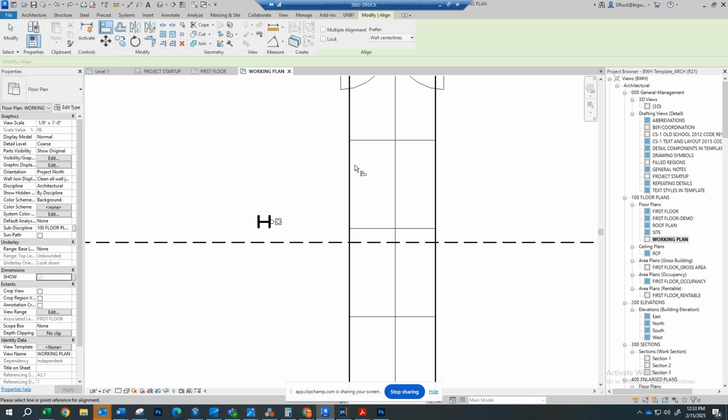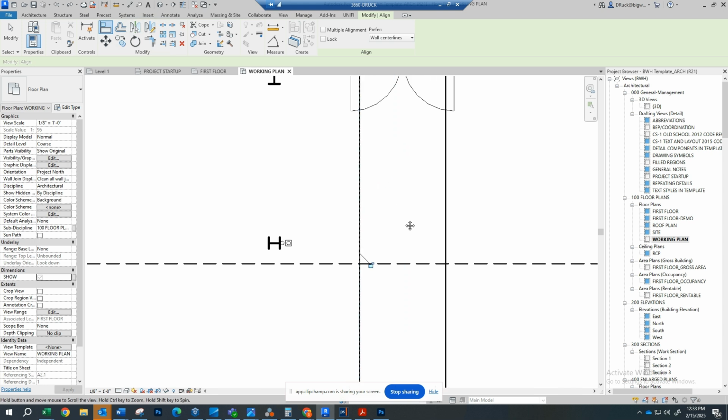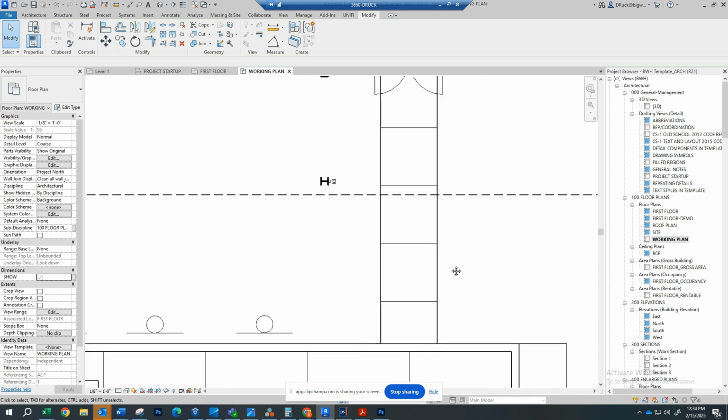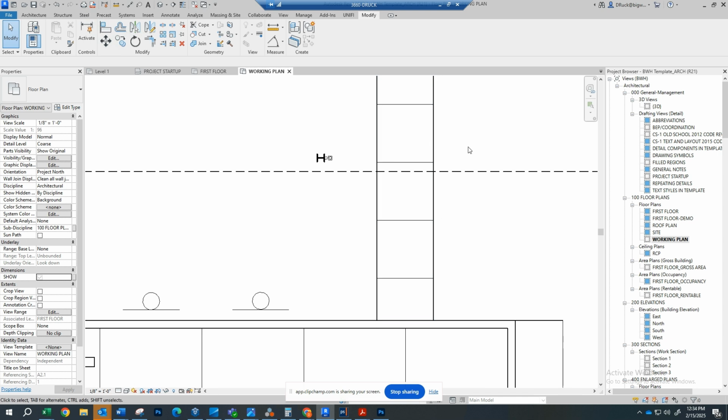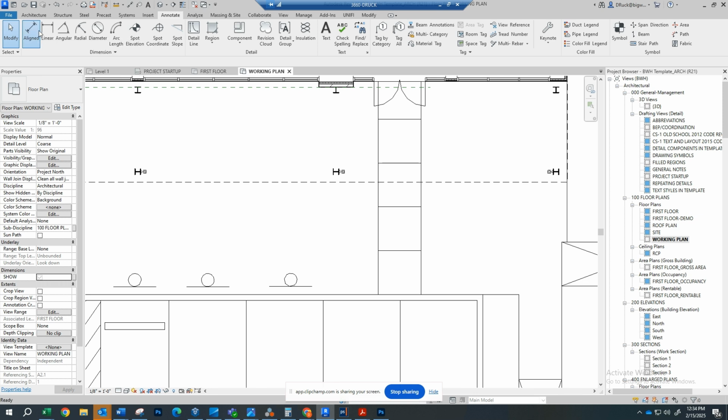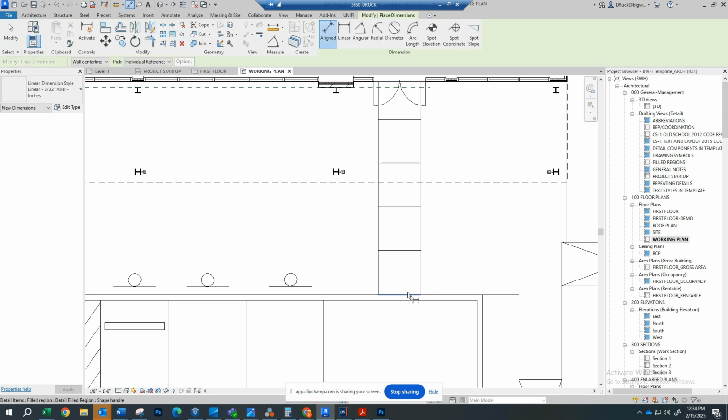So if you click on that, you click on the line you want something to be aligned to, and then you click the line and it's going to move it like that. So now you can see we got a nice 5-foot wide sidewalk, and you start the pattern from there so that if we take a dimension tool, so annotate aligned at the corner there, we can dimension to the sidewalks.